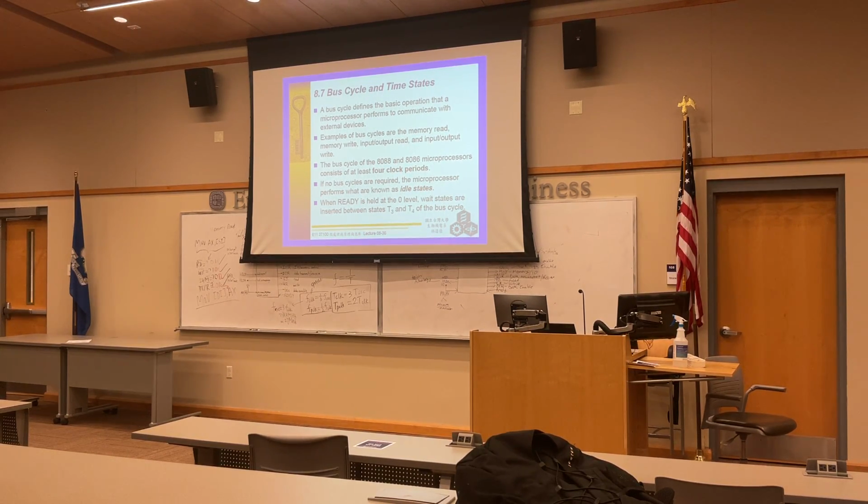See, right? So you see that you have multiple stages. Similarly, if you want to read data from memory, it's not a magic button. It's multiple stages. First, broadcast the address, telling memory where the data is. The memory is going to locate that piece of data and bring it to the data bus. And then from the data bus, it sends it to your microprocessor's destination register. At least 1, 2, 3, 4.